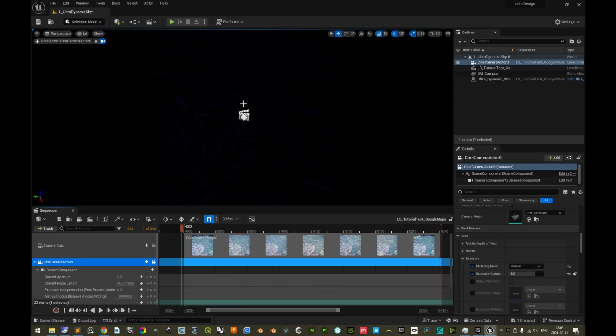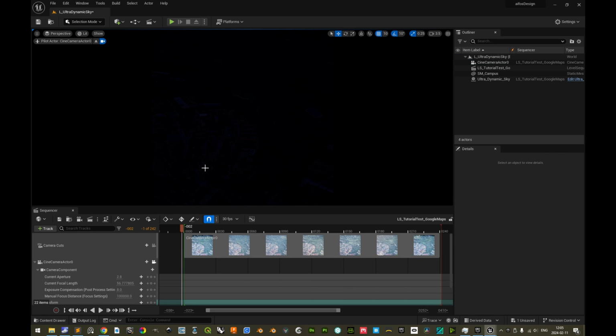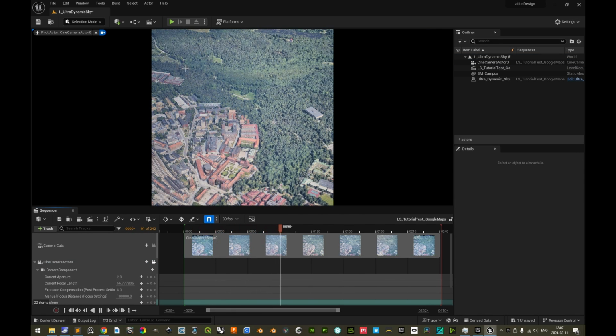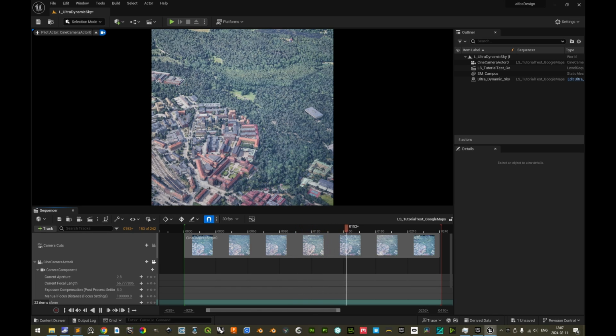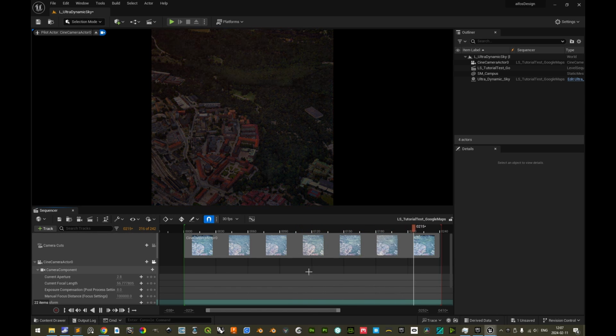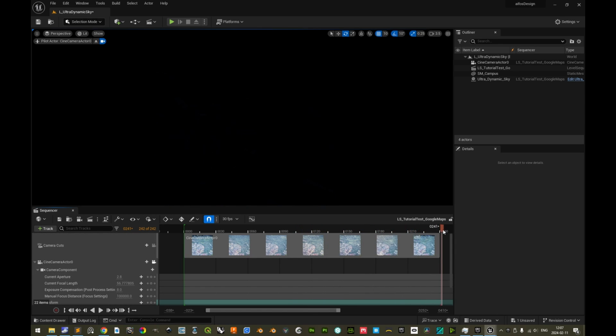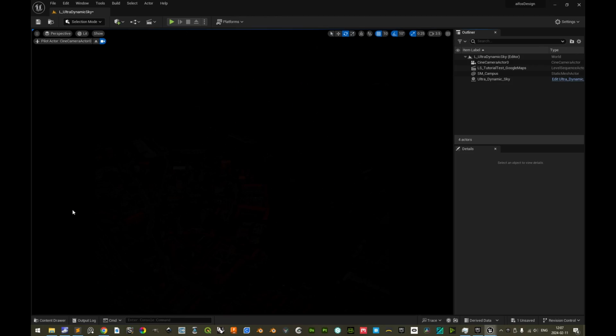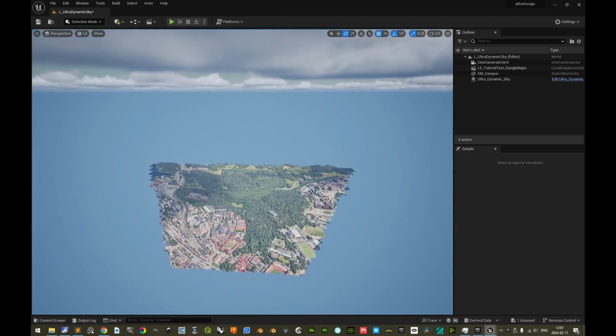If you want to get rid of that level sequence icon, we can just press G, while here, G, to go to game view. The addition of some camera shake might be advisable, but due to the time-lapse nature of the scene, it might be a little inconsistent with what we would see. So the one thing that we can add would be some depth of field. Let's see if we do like this. We can exit the sequencer and make sure to exit the piloting here as well.